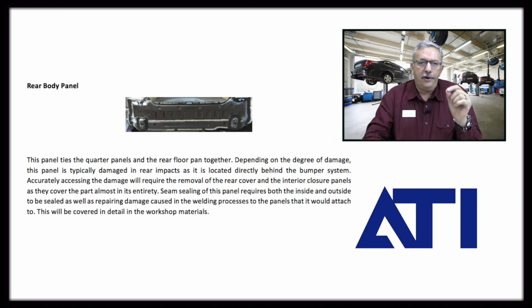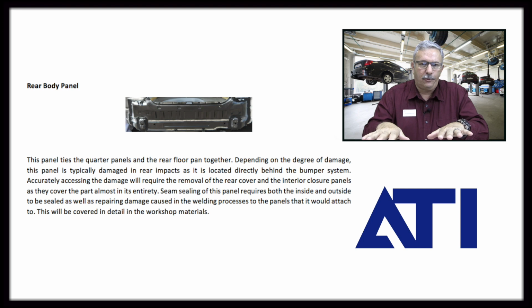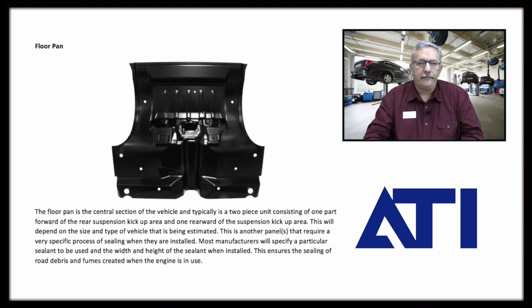But again, the rear body panel ties the quarter panels or the unisides together with the floor pan, and it does attach to the frame rails. So a pretty integral part in the structure of the vehicle. Speaking of floor pans, this will be the next item we're going to talk about. This is a major structural component in the vehicle.